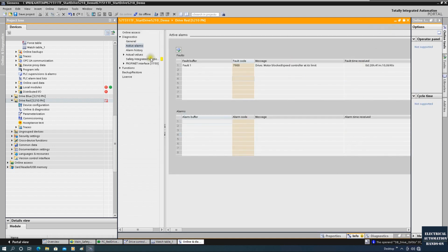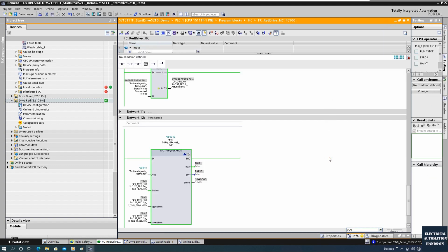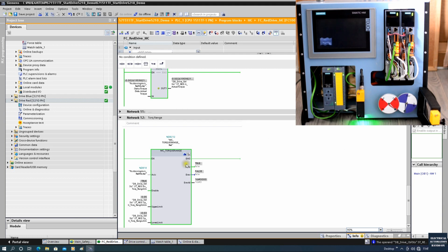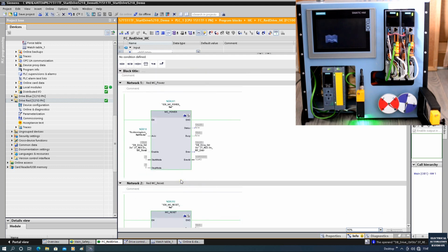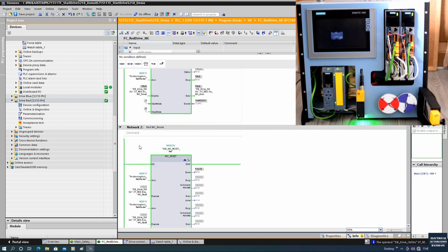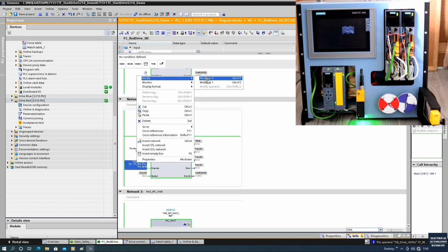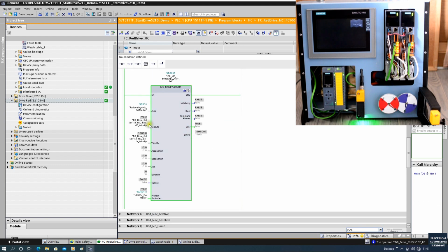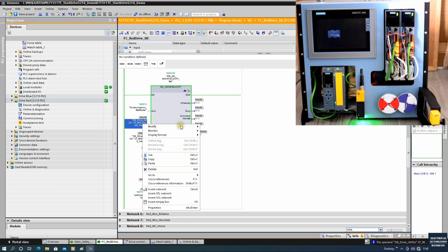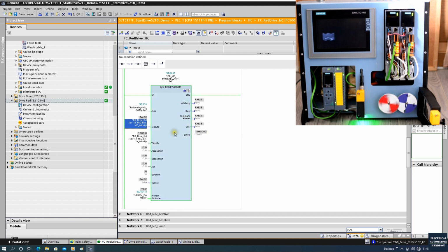And then let's go back to again. I will acknowledge this fault. Okay, we can try again. All right, now let's restart this motor. So firstly, power up. Okay, reset the fault. Okay, now the motor powers up. So I will trigger this motor velocity. And meantime, I leave this position controlled to true as a default. So let's fire. So now the motor is spinning, is running.